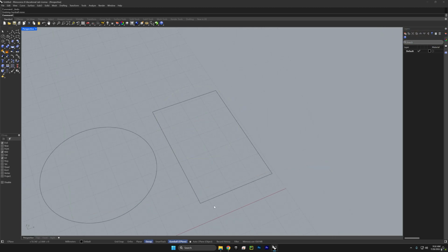Curves can also be joined together, but before we run that command on these 4 curves here, let's take the lower one and move it down just a little bit to illustrate something. And then we're going to use our lasso to select all 4 and join. And in the command line, it says that 4 curves were joined into 2 open curves. So the top 3 are together now, and the bottom one is separate because the ends didn't meet up perfectly.